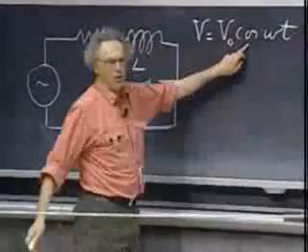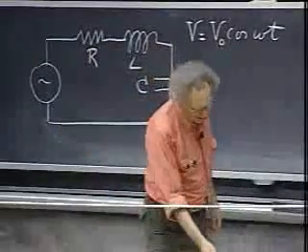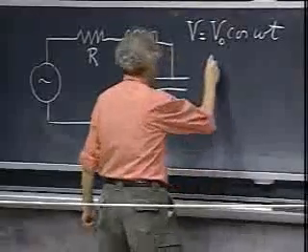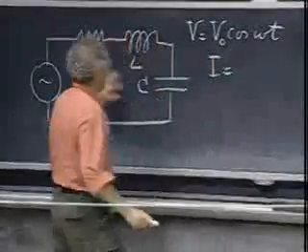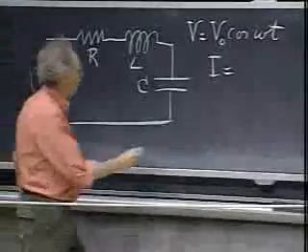Keep in mind that this can always be sine omega t, of course. There's nothing special about a cosine in life. The steady state solution, that is not when you turn the thing on, but if you wait a while, you get a steady state solution for the current.